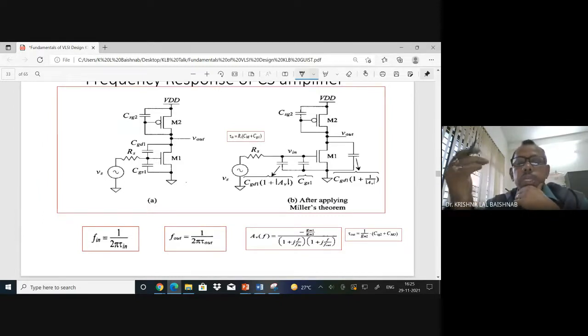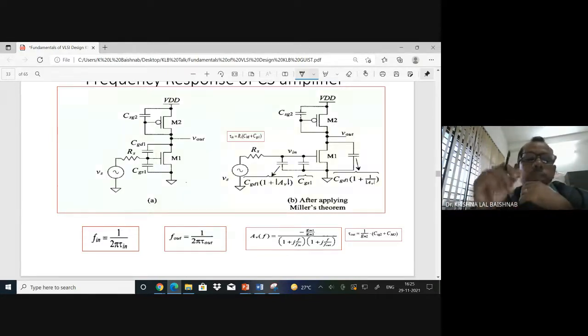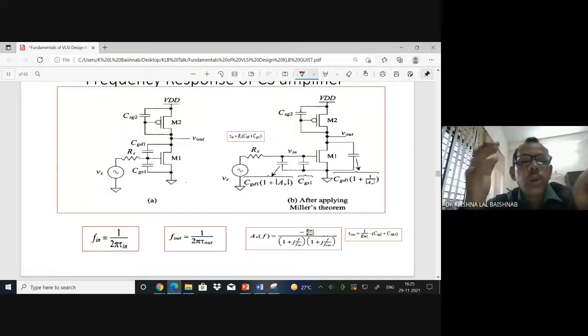Because we have studied so many, even in the third semester, fourth semester, we have analog circuit design, but we did not consider somewhere that at low frequency those capacitors are bulky, open circuit. Remember, in this circuit we have shown so many capacitances, but at low frequency these capacitors are very big, becoming open circuit. So these are not coming into play at very low frequency. And what we studied in basic electronics or analog electronics basics chapters, we just take a transistor and try to design an amplifier, because in those days knowledge was not to that extent.